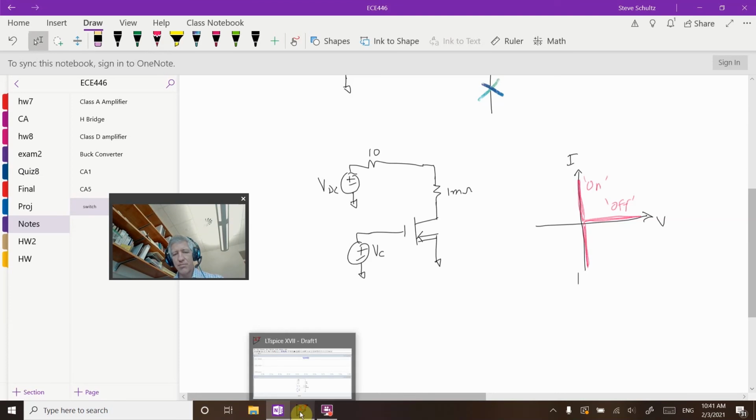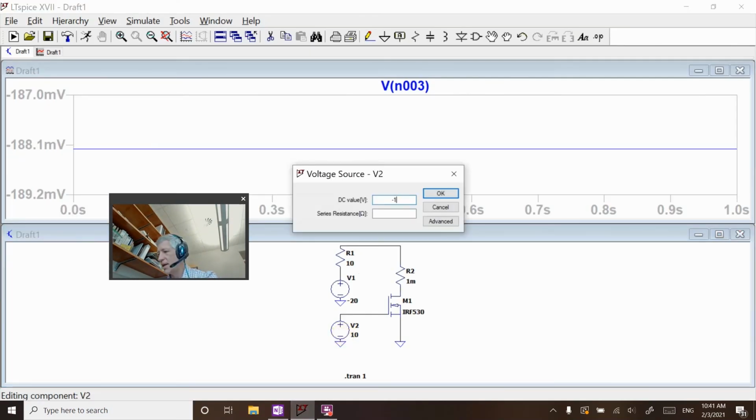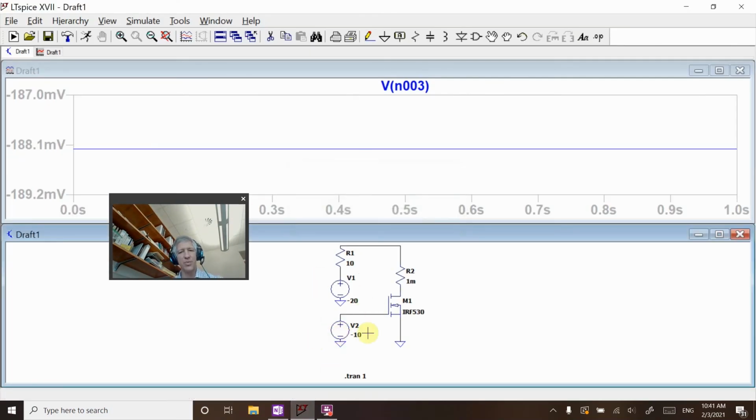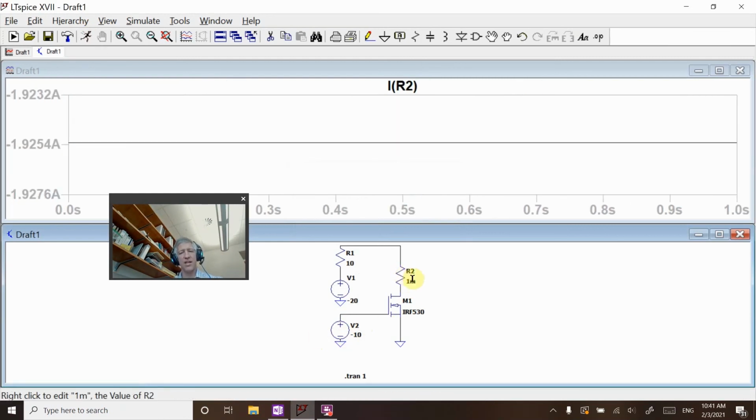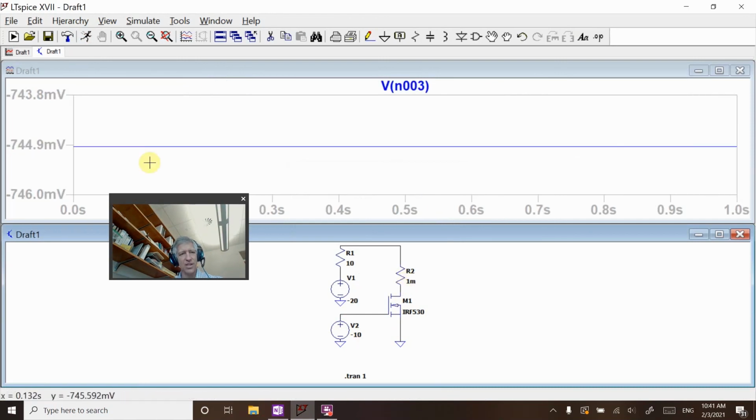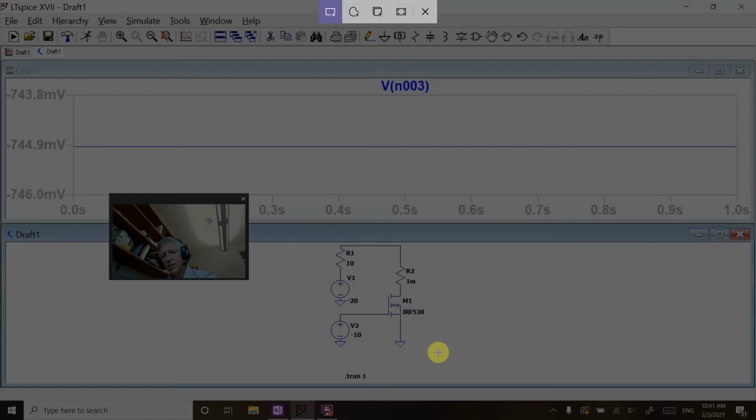So now we just want to turn it off, and I make it minus 10 volts because this should be a nice switch. This should be off, and I run this and we get current. Well, my transistor's gate to source voltage is less than 0, less than the threshold. We shouldn't have anything on there. Let's look at what the voltage is. Oh, it's 0.7 volts. Okay, so what happens is that I can't turn it off if it's in this reverse configuration. So basically, let's just copy this over.